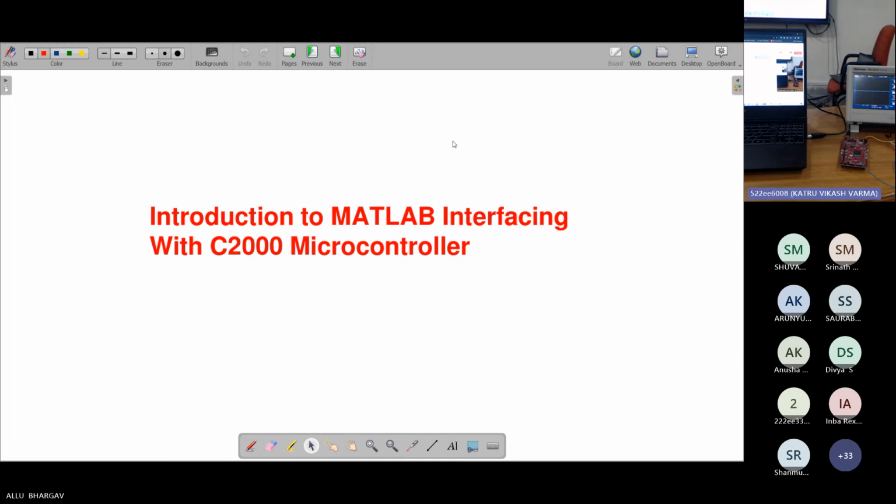Before going to access the peripherals of the C2000 microcontroller, first let's see how to install the C2000 microcontroller block set in MATLAB, and then how to interface the C2000 microcontroller with a particular Simulink file. Then we will see how to access the peripherals like ADC, DAC, GPIOs, and EPWMs. So we're going to the MATLAB file now.